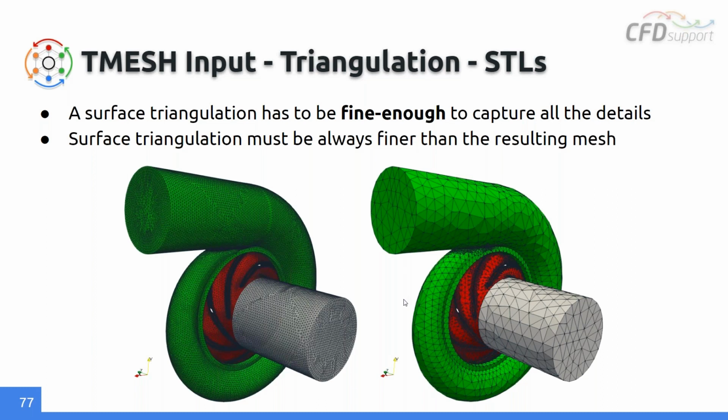Sometimes, if you export the STLs from CAD software implicitly, just with save as STL, the STL is usually really rough, and for highly curved areas there are just zigzag shapes, which give you a huge error in the resulting CFD simulation, because you are simply simulating something different from the original shape.